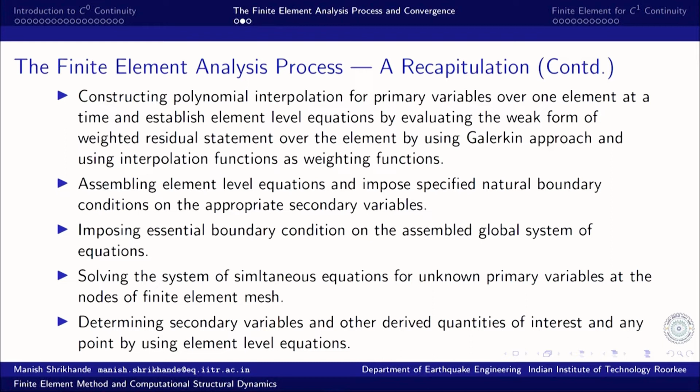And once we find the finite element solution for the primary variables, the secondary variables and other derived quantities of interest may be computed by reverting back to element level equations with known values of the primary variable at those nodes of the element. So, this in essence is the entire finite element process. The difference only happens, for different problems, as I said, we have different kinds of interpolation functions and different types of finite elements, but the rest of the process remains the same.